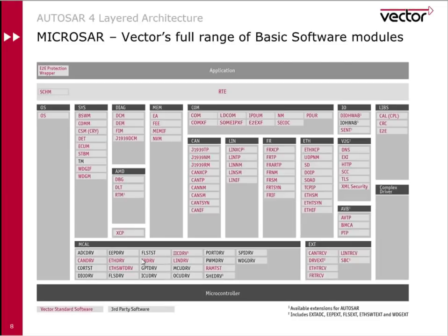And this is to present the basic software above with a common API to access the hardware and provide common access and common functions for the hardware, regardless of the hardware implementation underneath. Typically, the MCAL layer will be provided by the silicon vendor. So, for example, if it were an Infineon processor, you would source the MCAL software for Infineon. A Freescale processor, you would source the MCAL software from Freescale, for example.